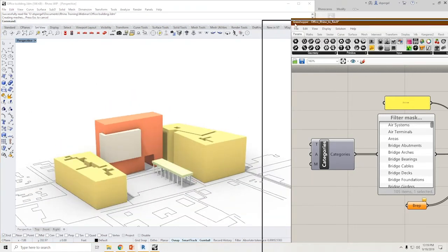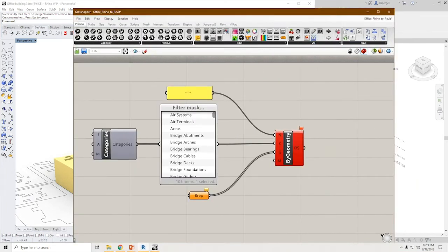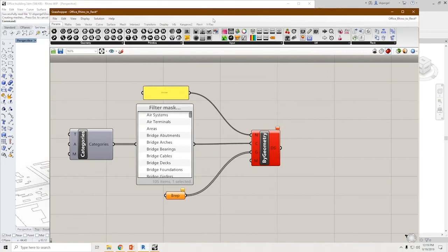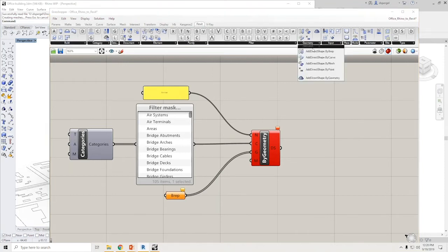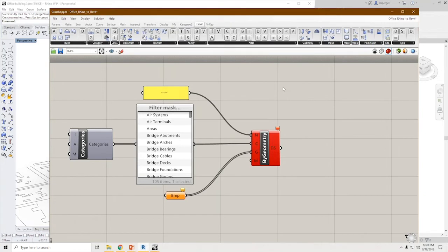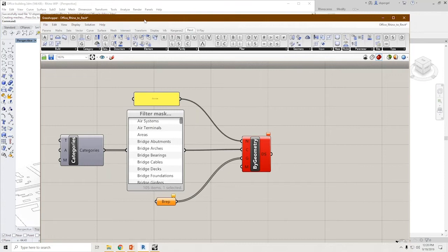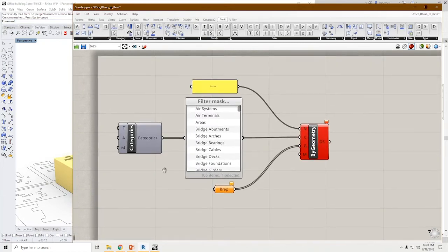And then I loaded up my Grasshopper script, and if you're familiar with Grasshopper, you might notice a new tab up there at the top, Revit. Here are all the different Grasshopper components that you can use to hook into Revit from Grasshopper. You can pull out the geometry, filter by elements, and this is reading it all from the same memory space as our Revit file that is open in the back there. Like I said, no importing, exporting. They're reading the same language.